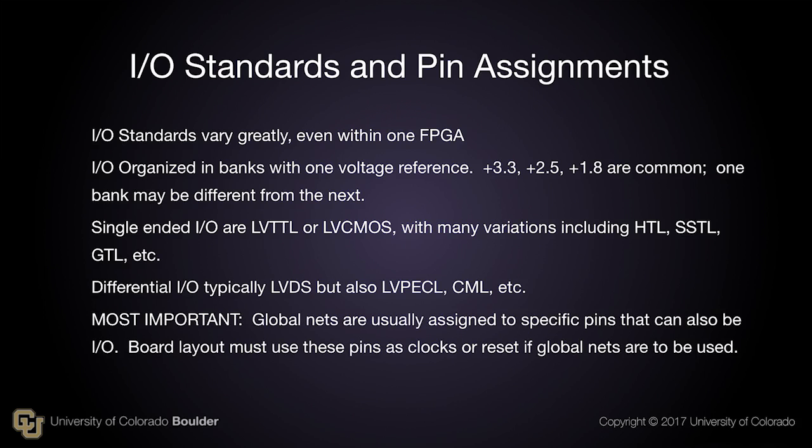One of the most important things to remember is that global nets are usually assigned to specific pins that can also be I/O. Board layout must use these pins as clocks or resets if global nets are to be used. One of the most common mistakes I've seen as a consultant is the PCB connection of a clock signal to a pin that has no access to the global network in the FPGA. This can be easily avoided.